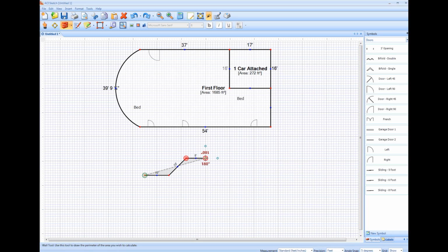To bring this one home, it's just hitting 10 on the keyboard, and I'm going to be bearing right, so I hit R, 45 to make my angle, and enter, and there it is. So let me hit delete a couple times to back out of that, and I'll show you some other alternatives. I used 45 as an example because it's a common angle, but it could be any angle.